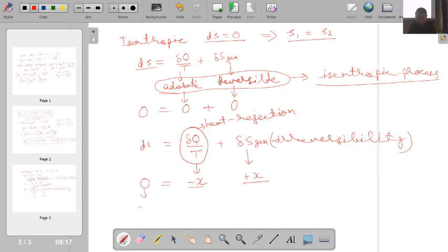So the meaning of left hand side 0 means we have nothing but the isentropic process, but it has irreversibilities and it has heat transfer. So it means all the isentropic processes may not be reversible adiabatic. But over here in our present formulation of compressible flow, whenever we will be referring to the situation of isentropic flow, majority of the time we will be nothing but pointing towards the reversible adiabatic flow.